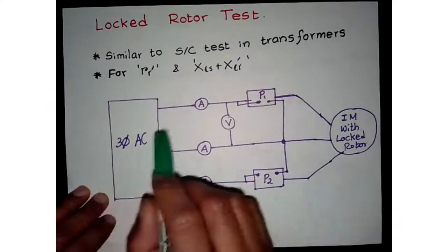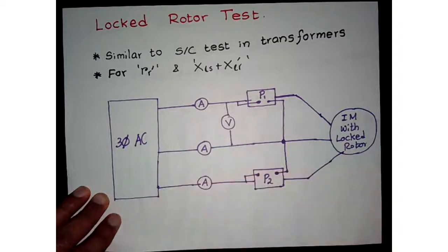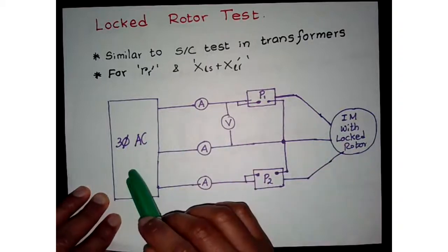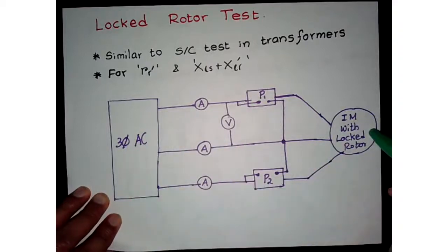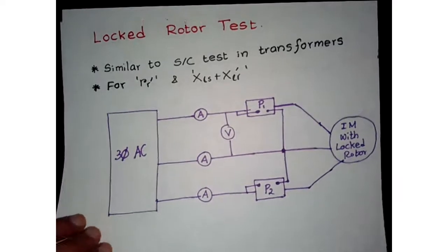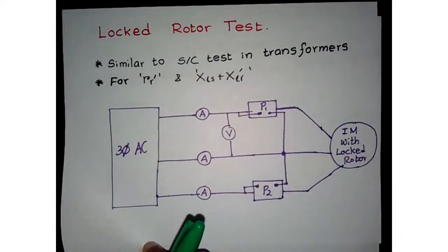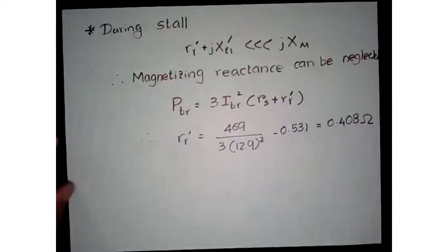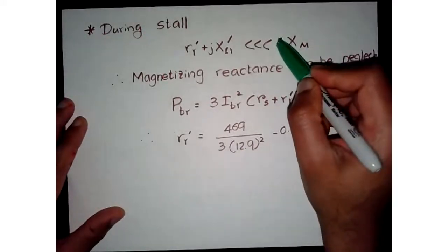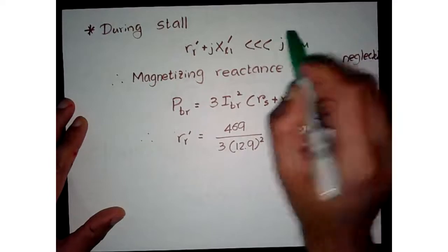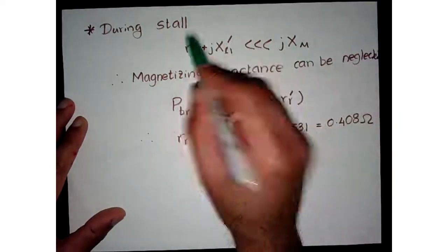We again, similar method, we are setting up to apply three-phase voltages. The machine is locked, therefore use lower voltage than the rated, okay, and also lower frequency, but we have to consider that in the calculation. All right, okay, so during stall, our magnetizing flux is much larger, therefore the smaller terms will dominate.